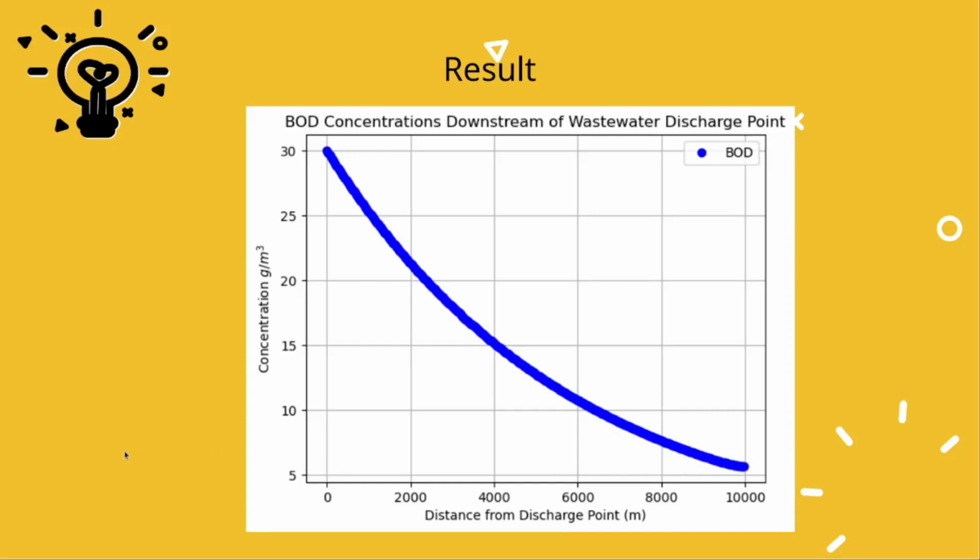So there could be some limitation that says, what is the distance before a next treatment plant can put in waste. So we have to make sure that this concentration goes sufficiently low before the next city gets its opportunity to discharge waste. Otherwise, we are adding waste too quickly, which will in turn cause fouling of the river, BOD accumulation, and other problems.